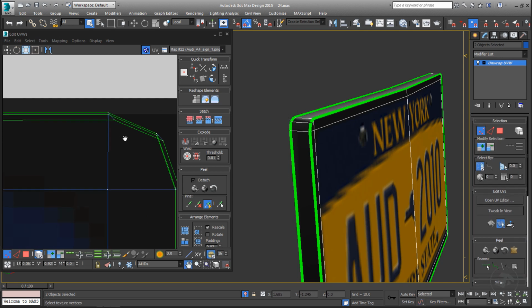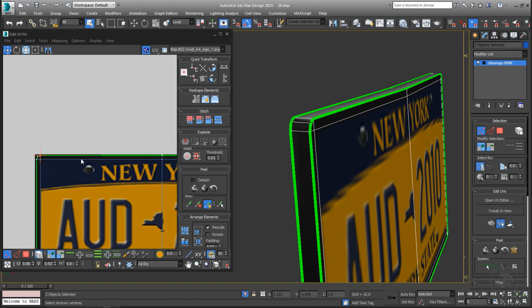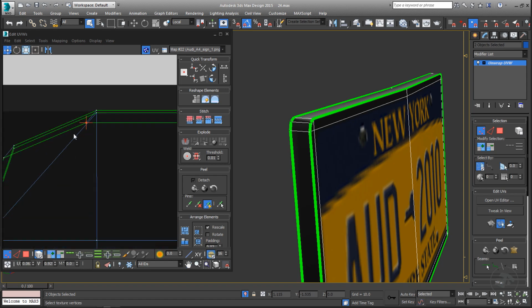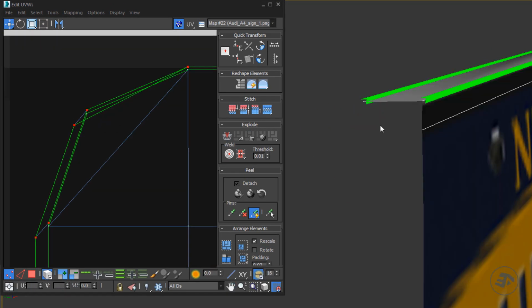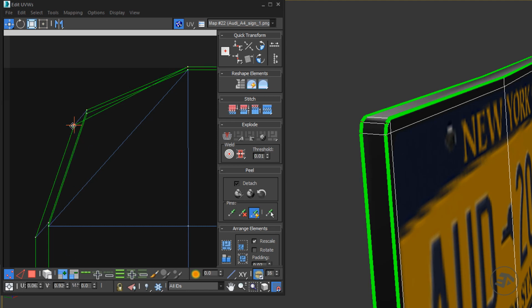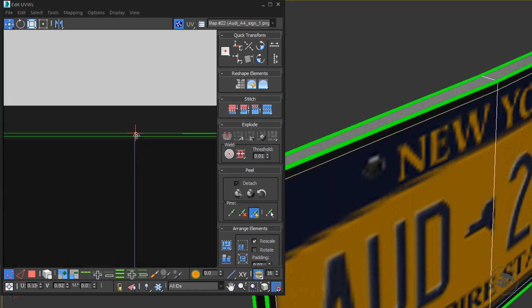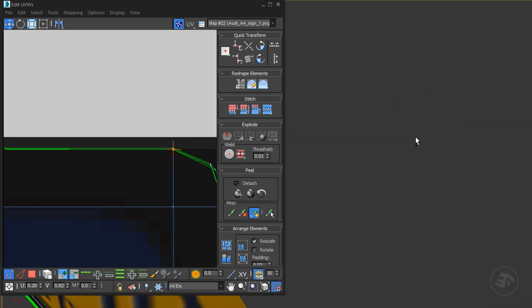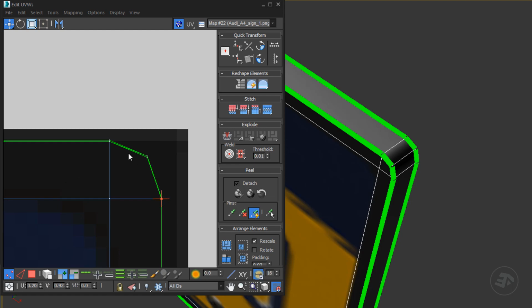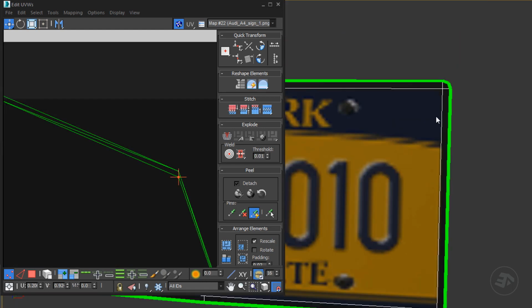There are two approaches to achieve this. One of them is to correct the UV map by overlapping the frame vertices with respect to the UVs that represent the license characters. Inside the UVW editor, activate Snap to Vertices, then move the out-of-range vertices inward until they overlap their obverse. If you get confused, try to select the out-of-range vertices from the viewport.